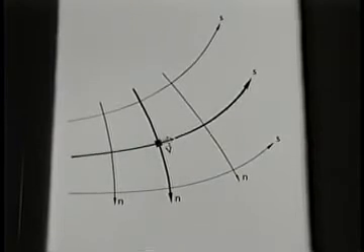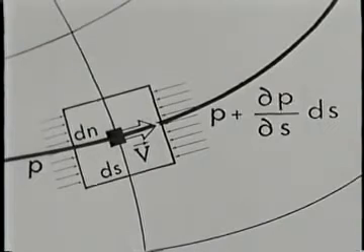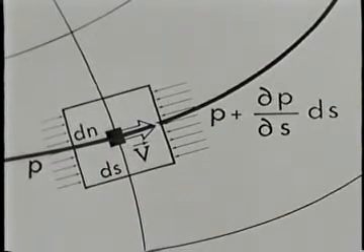v along S. Here is the particle enlarged. Since there are no viscous stresses, the normal stress at a point is uniform in all directions. It is a scalar, which varies from point to point.